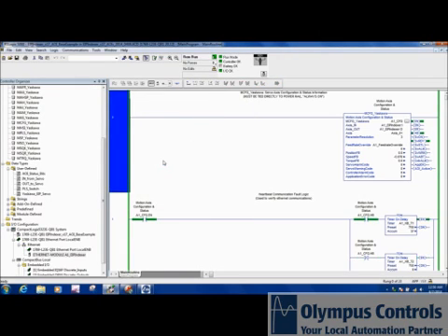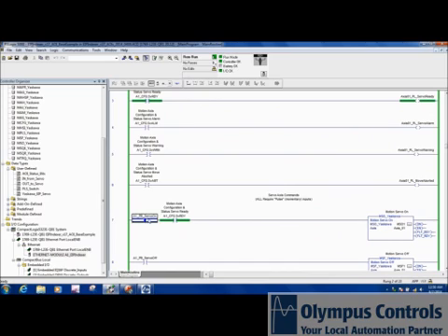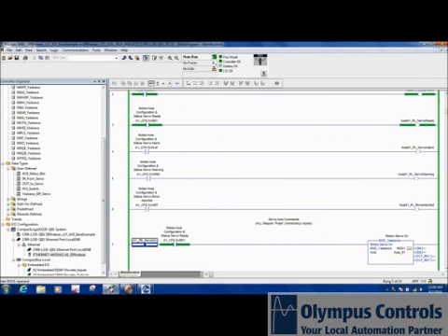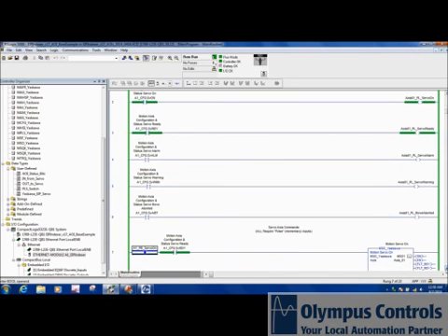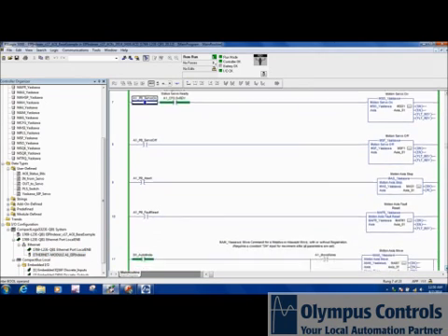And now my PLC program is running, and the first thing you'll notice is that it's already connected to the Yaskawa drive. It's got a heartbeat going on. The servo is not on right now, so I could come down here and toggle it on. I click Control T. I just need a one-shot toggle of that servo on, and you'll see now that the status is that the servo is ready and the servo is on. So that's it. All I had to do was open this sample program, change the IP address of the drive, and then download it to the PLC. And I'm connected, I'm talking.